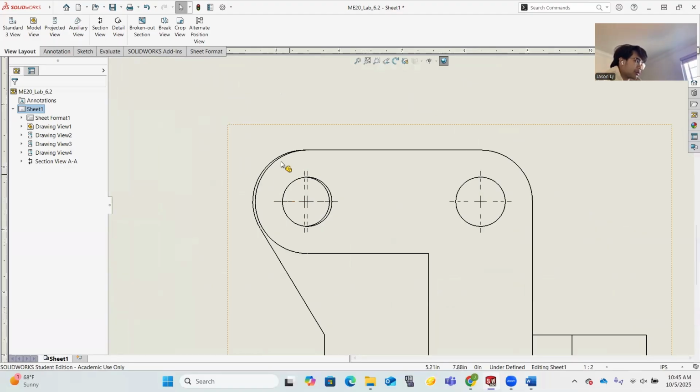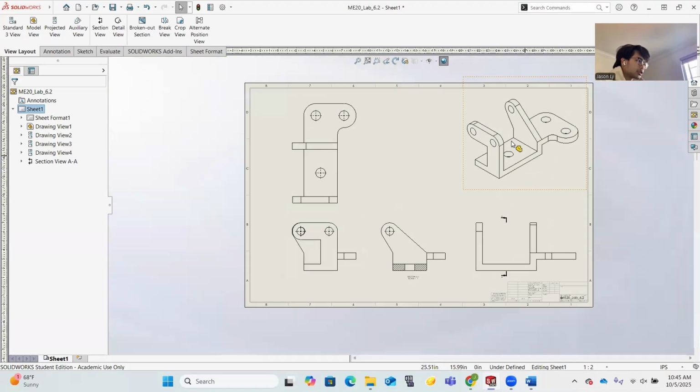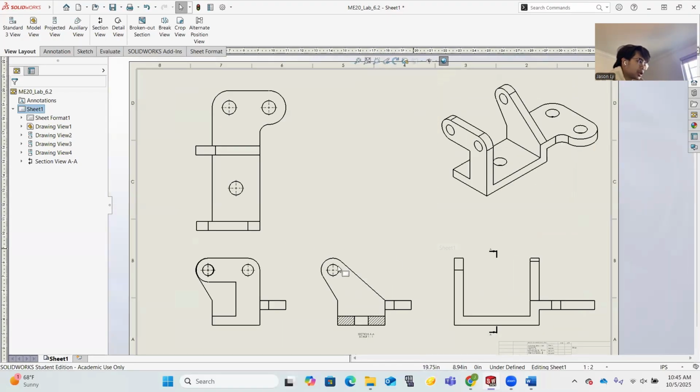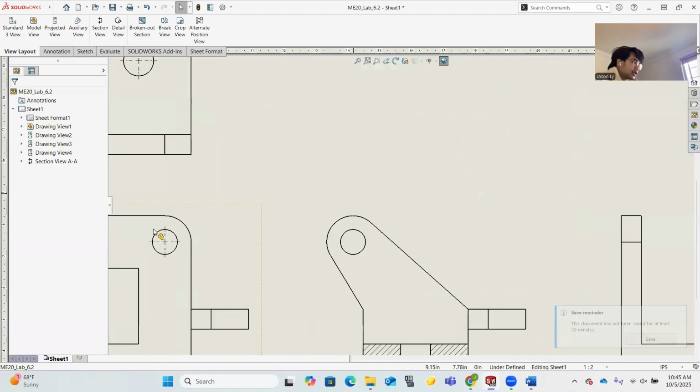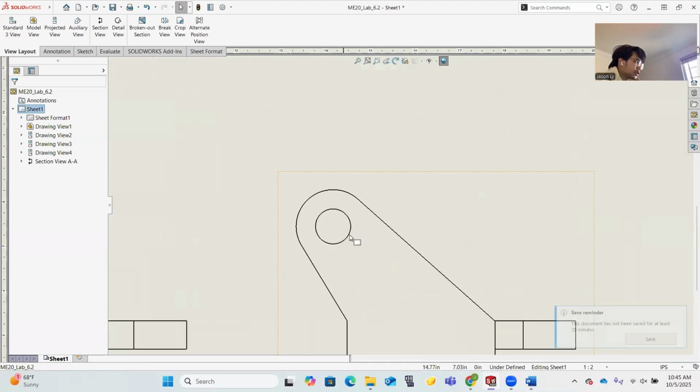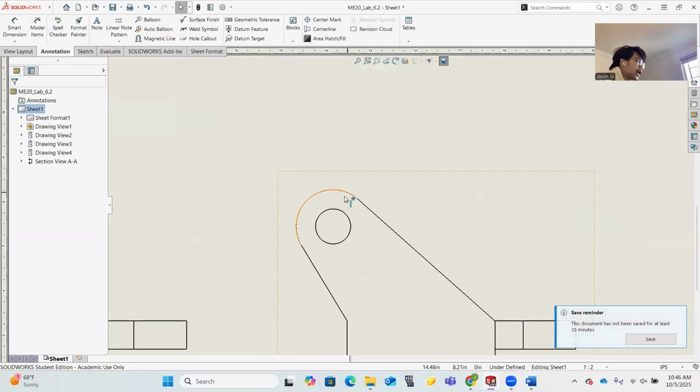And of course, remember your part is supposed to be offset like this by 1 millimeter. That's the correct direction, so don't worry about those holes being concentric. And if you guys have any circles, right, that didn't have this dotted line cross section, that's called your center mark. So any circular hole or feature, make sure you put a center mark. It'll help you dimension as well.